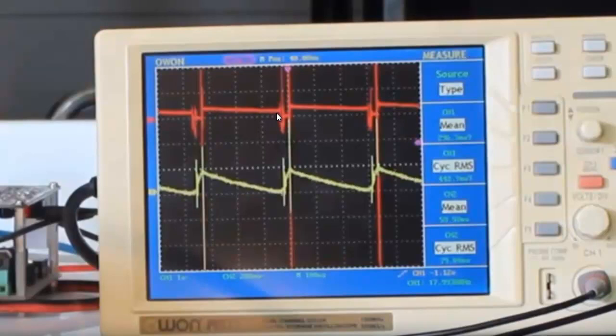Remember, this is just a very simple experiment. This is a throw together, if you like, from a symmetrical transformer to an asymmetrical transformer, and we just luckily had a little bit of success with it. This is something that I have not played with, I have not tuned it, I've not done anything to it other than throw the coil on and give it a 10% duty cycle at 3 kilohertz. So this is non-tuned, non-everything. This is just, here it is, it's working, this is what you need to look for.